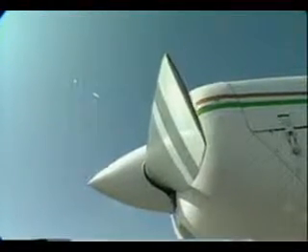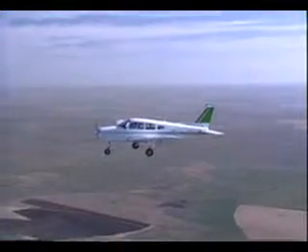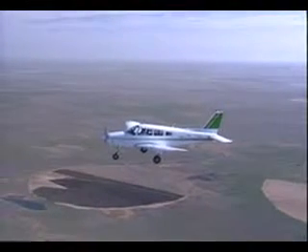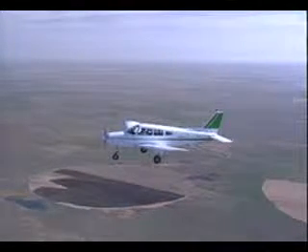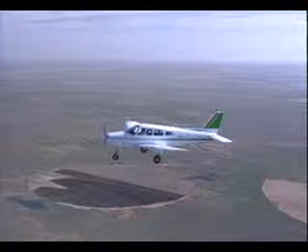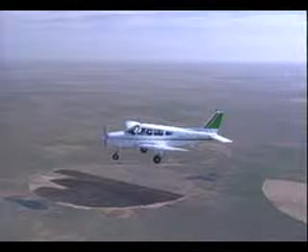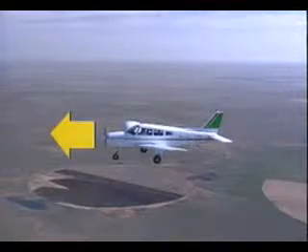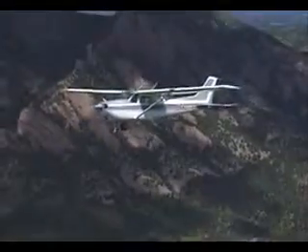If you look closely at a propeller, you will notice that it looks like a twisted airfoil. As the propeller turns, a lower pressure area is created in front of each rotating blade. The low pressure in front of the propeller, like that above the wing, provides lift which acts forward. This forward-acting lift, or thrust, moves the airplane forward.